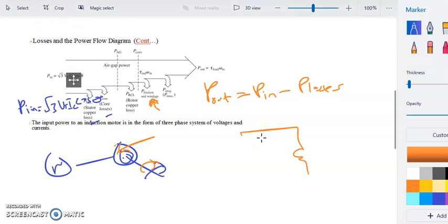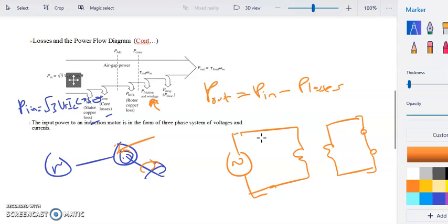In terms of concept, actually the induction motor is just like our transformer. We have a transformer, it comes from the AC source to the primary coil, then transfers to the secondary coil. The difference is that in the induction motor, we have a short-circuited secondary. So instead of transferring energy from electrical to electrical, now we are transferring energy from electrical to mechanical. It means we are rotating this secondary part, and we have a high current that flows into the secondary wiring or secondary circuit. So the current will push the secondary to turn.